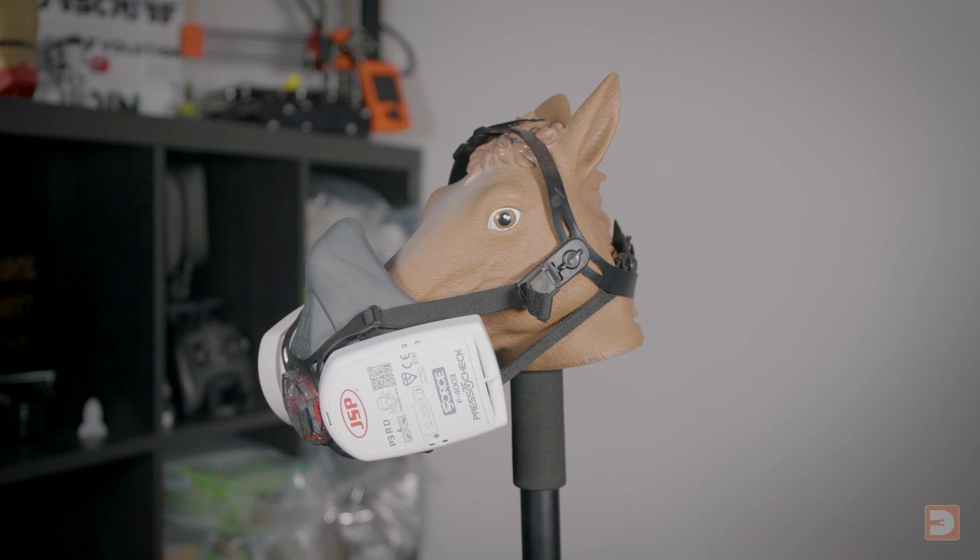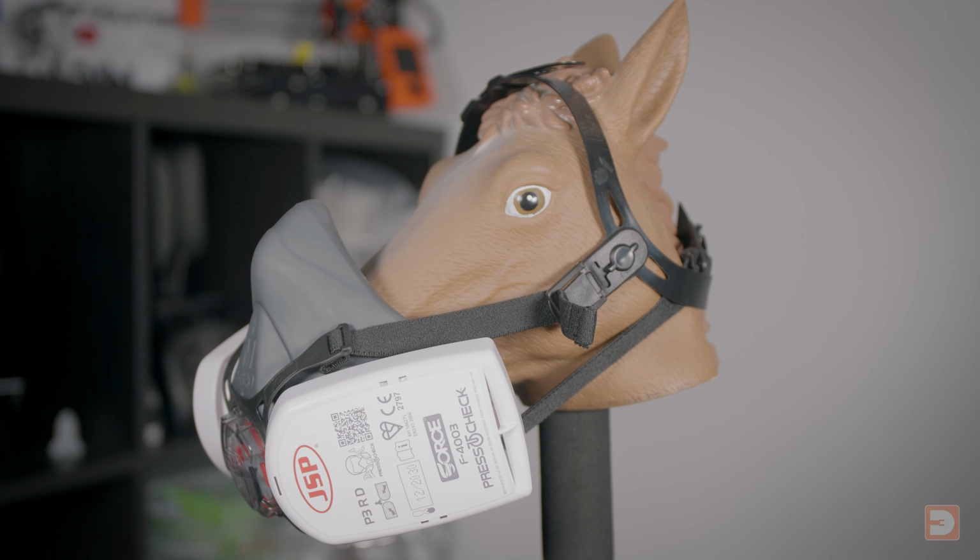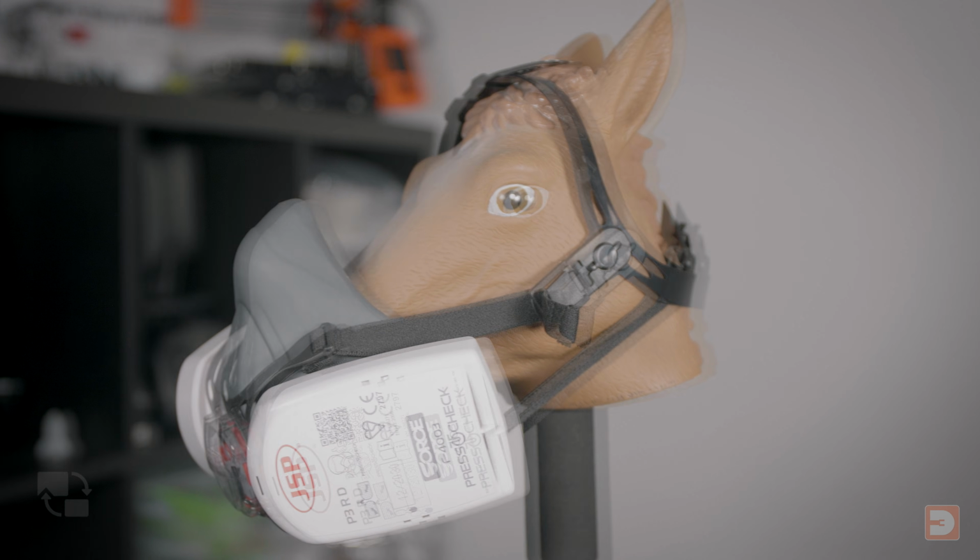It's important that each photo you take has a good overlap with its neighbouring images. This is because there needs to be enough uniquely identifiable points which you can see from multiple images. The object you're scanning should cover at least 60% of the frame, and ideally they should overlap by around 70%, so you should only make fairly small movements between each photo.